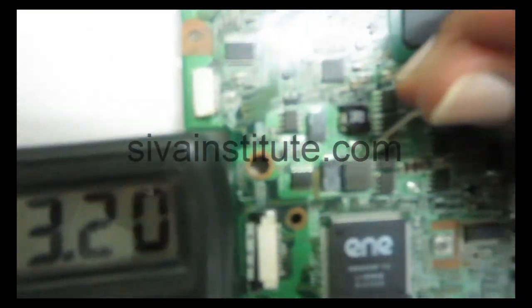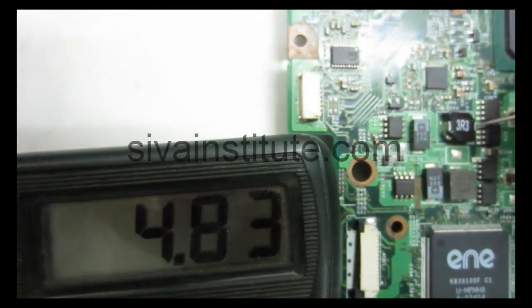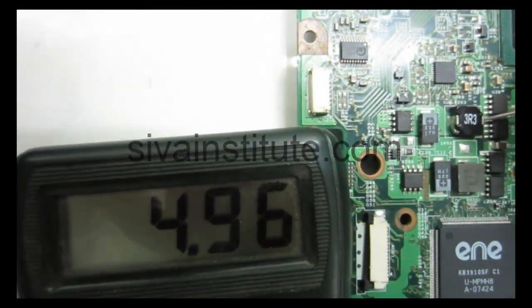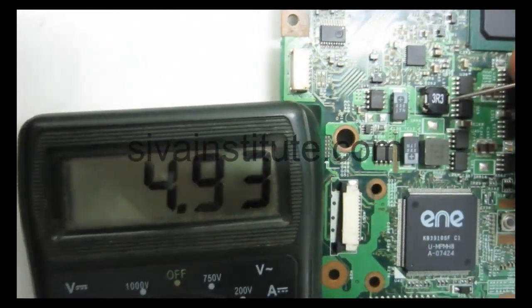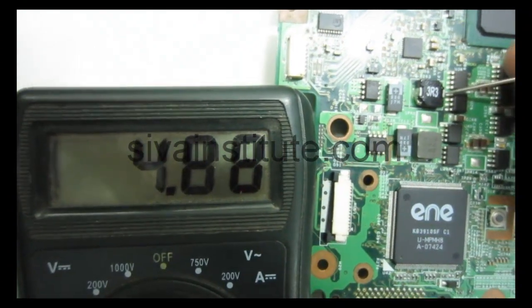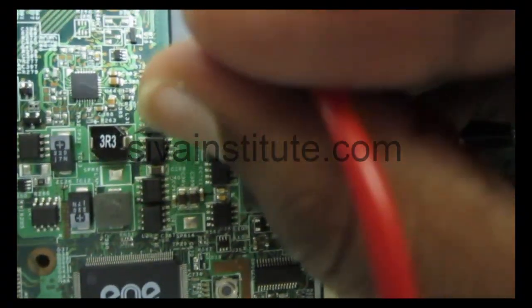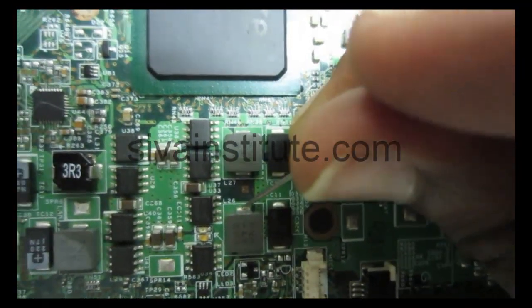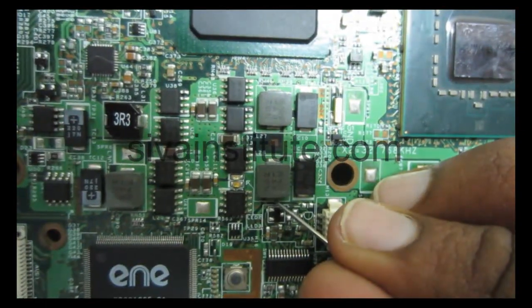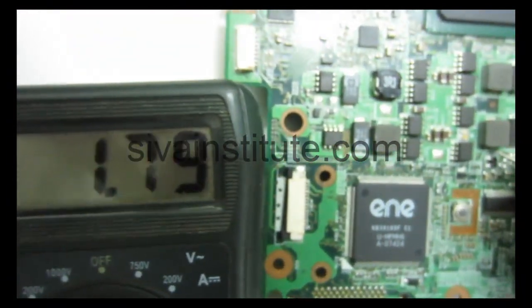Next, see at that coil 5 volts. See 5 volts. 4.7, 4.8, okay, 4.9. This voltage is okay. 3.3 volts and 5 volts are okay. Now we will check the memory supply, 1.8 volts, at this coil. Okay, 1.8 volts memory supply. 1.79, that means 1.8 volts.